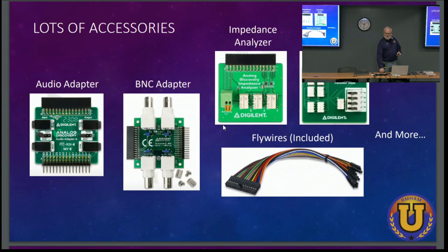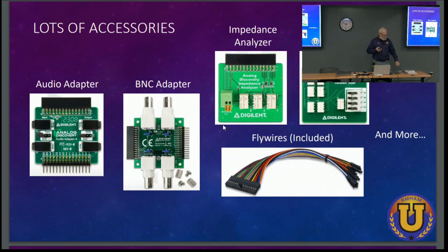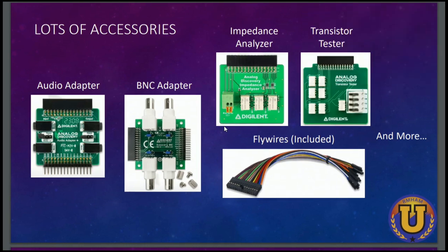One of the things that's really cool about this is there's a double row, so it's a 30-pin connector on the end. And if you want to use oscilloscope probes, you plug on the BNC connectors, and now you've got a pair of oscilloscope channels and a pair of waveform generator channels. So you can use it for measuring filters, for example.